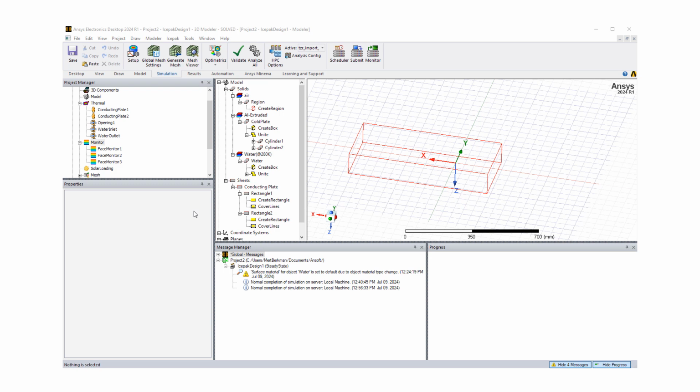We executed the model. So the next step is post-processing, which is actually a critical step where you get to look at the solutions. You want to make sure the results do make sense, because there are lots of sources of error, such as maybe meshing quality, picking wrong models, inputting wrong numbers, etc.